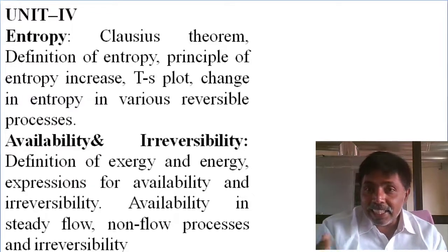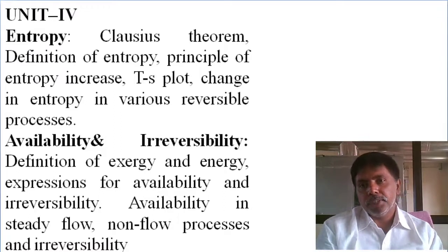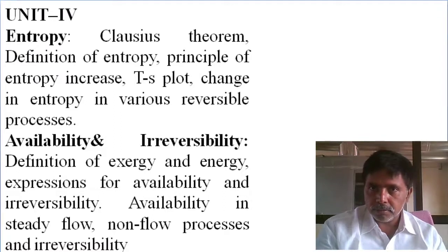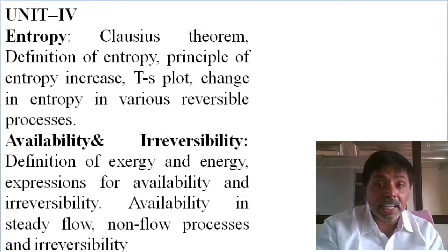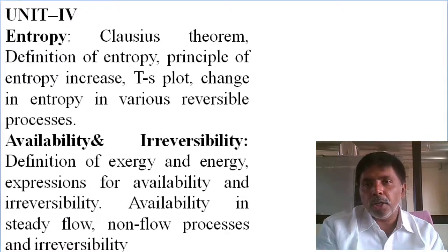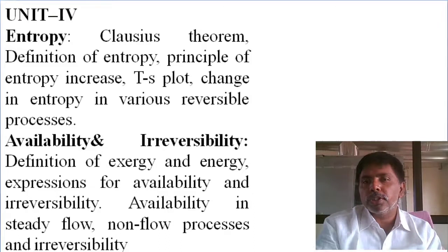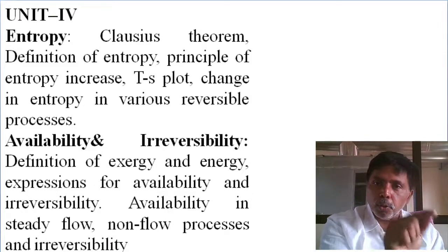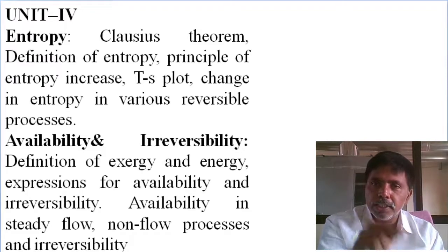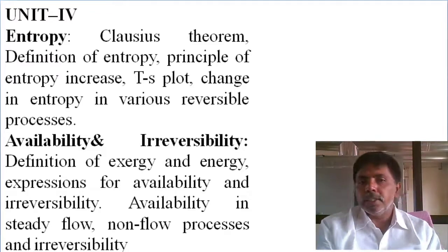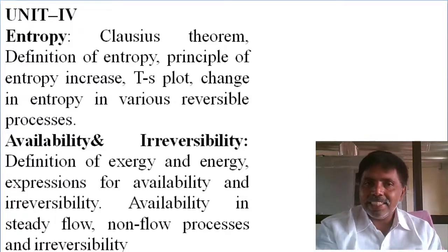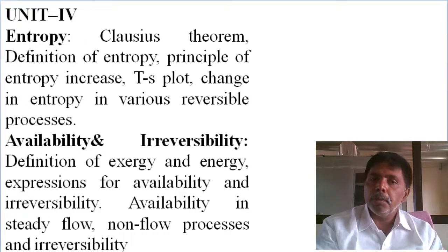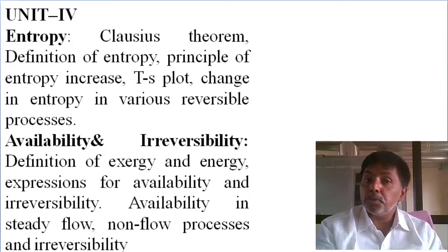With exergy, realistic designs come into the picture. Availability is there, capacity is there, but what is the capability? Based on the environmental condition and the process, the capability is changing. For that determination, the basic property we want to calculate is entropy, molecular disorderliness. So the Clausius theorem, definition of entropy, principle of entropy increase, and change in entropy in various reversible processes we are also deriving.